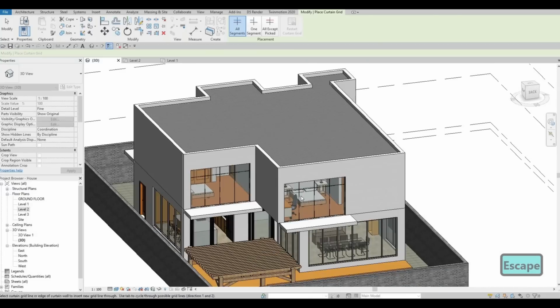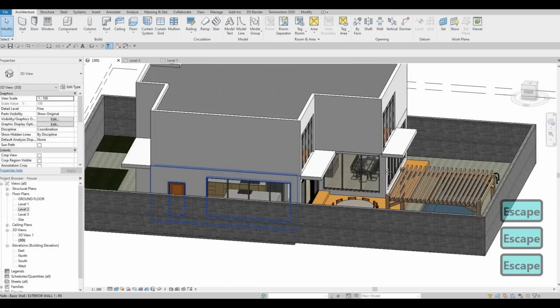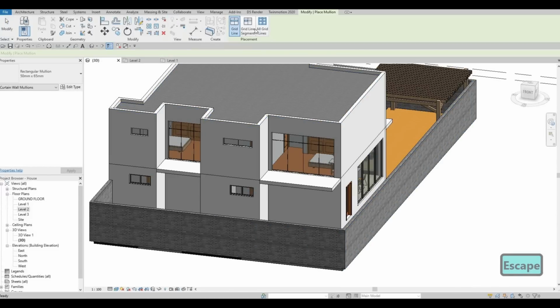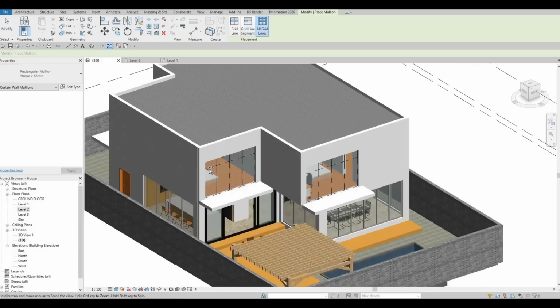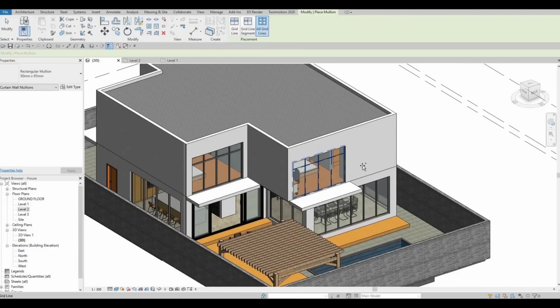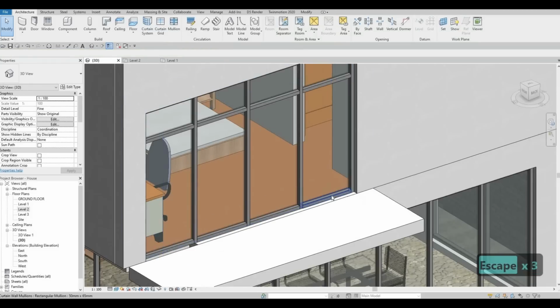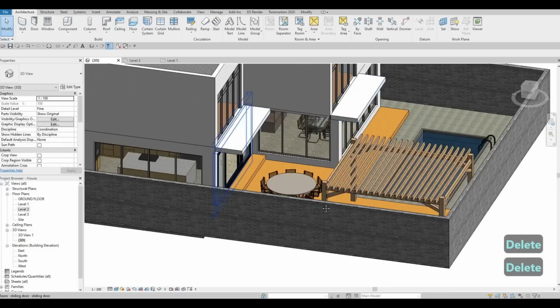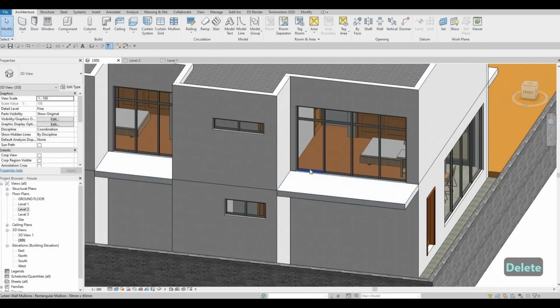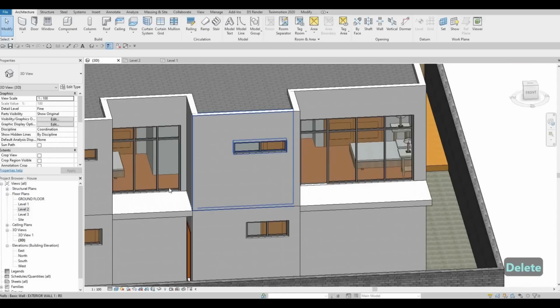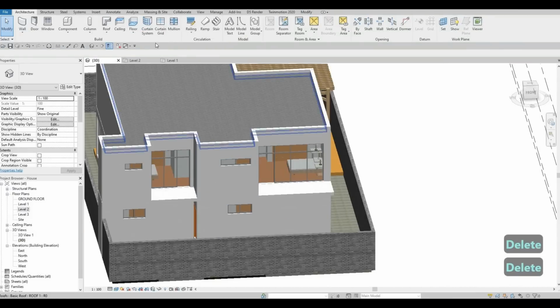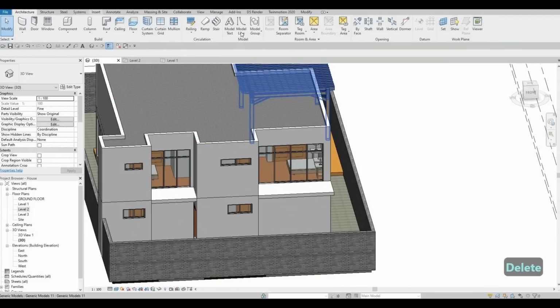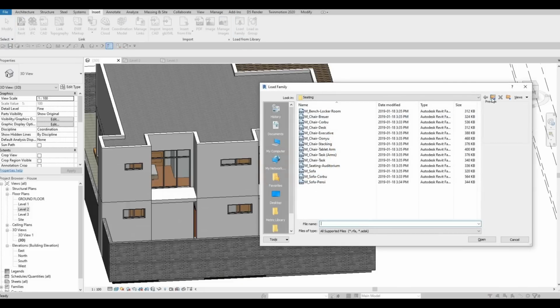And then before we add mullions, actually we could add the mullions now. So click on mullion, all grid, and then 50 by 65. So select that right there, and then obviously we need to add the door. So I'm gonna add it here. So we need to delete that because there shouldn't be a mullion if there's a door there. So delete here and then delete that.